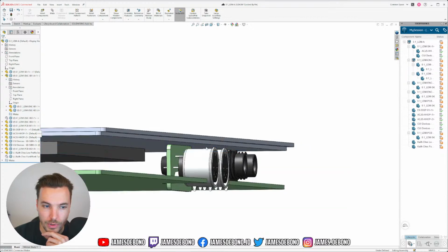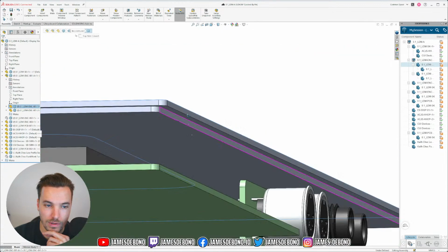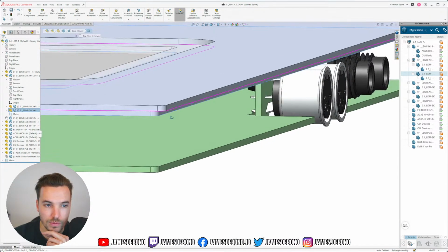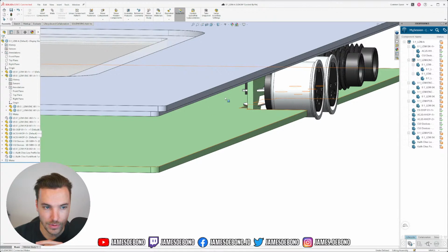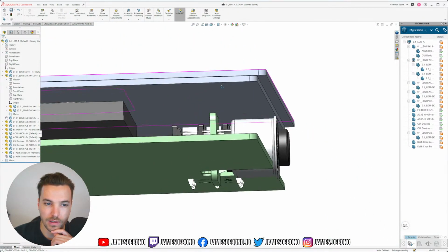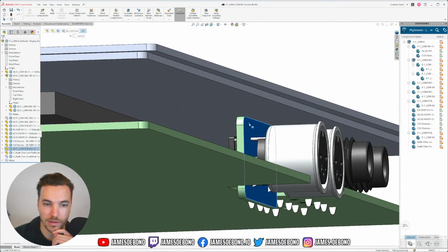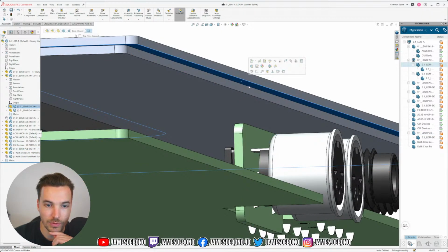So my top plate, I have like two layers. So this and this, which are currently two 1.5 millimeter thick aluminium sheets that are attached to each other, I don't know, with some adhesive or spot welded or something. And what I was thinking is if I made this PCB tall enough that it reaches the underside of this PCB, so this blue face, then I could have a little slot in this bottom plate that PCB fits into.